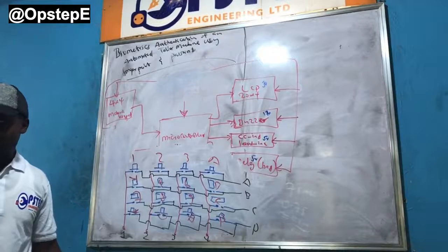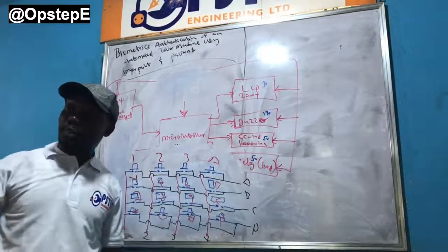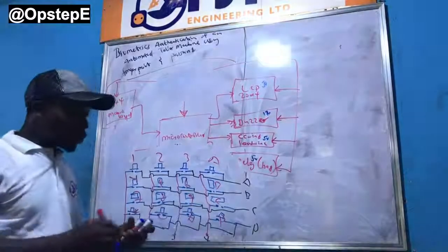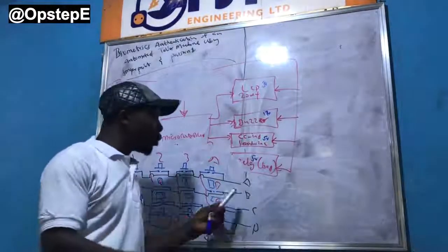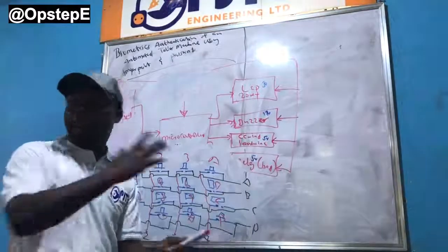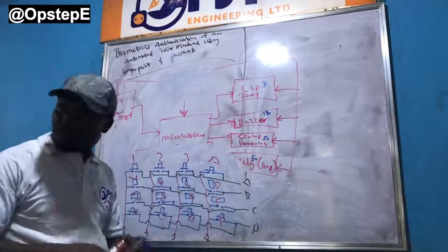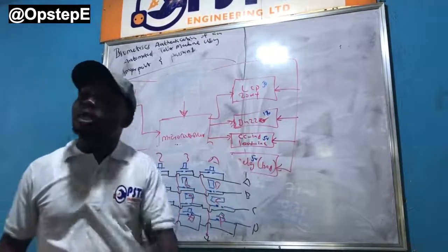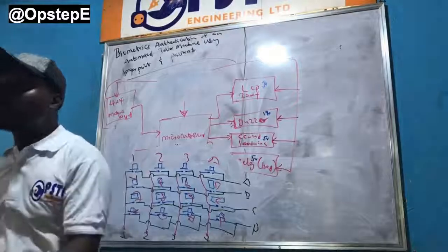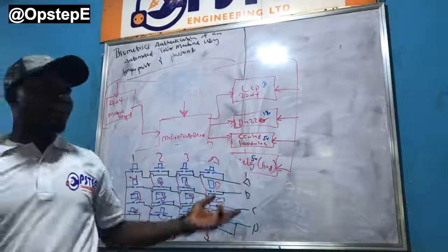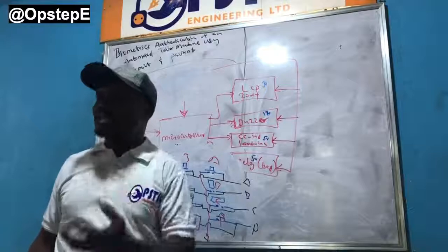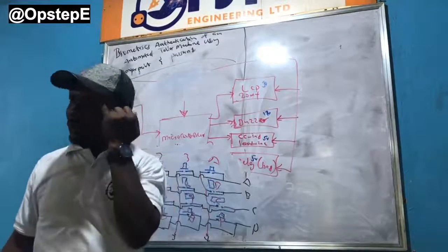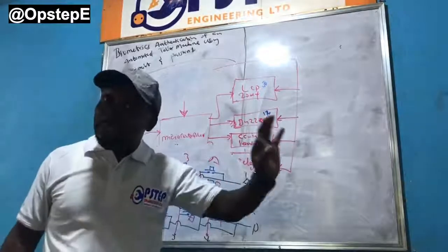Does it make sense? And you already know from what we discussed before that if you need to attach this to a microcontroller, you are going to need to actually have pull-ups on these pins, at least the ones that are acting as input. So you're going to need 4 resistors, 10K resistors. But since your port B offers you internal pull-up, there's no need to put the keypad on any other port on the microcontroller. That's why most systems that are designed without the pull-up resistor have the keypad attached to what? The port B, not port D, not port A.